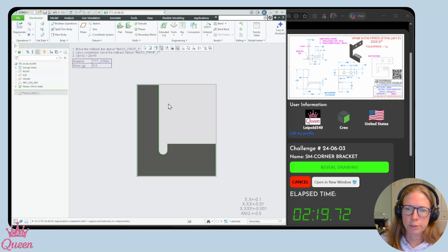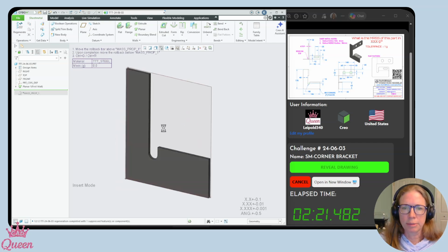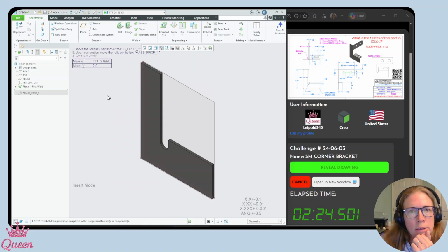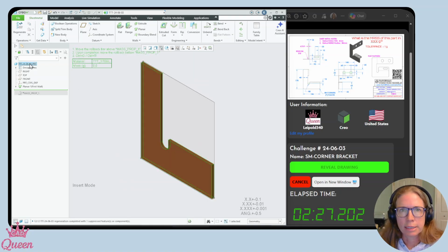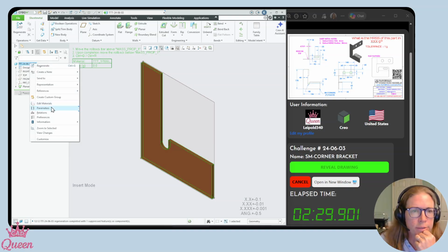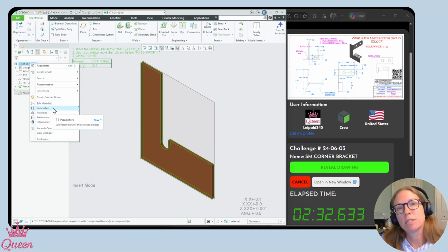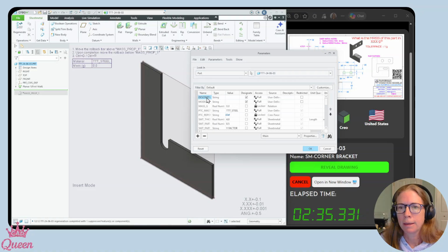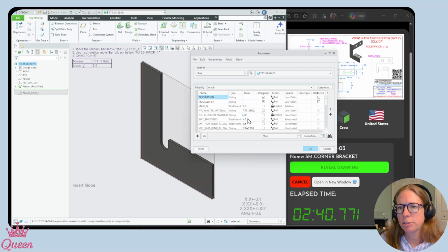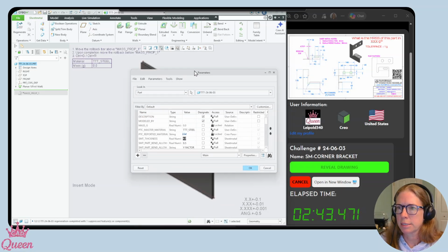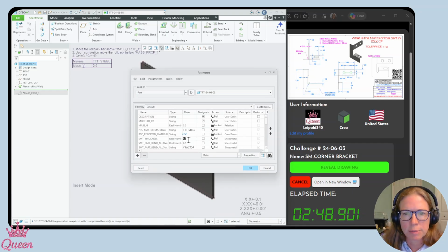Okay, so there's our planar first wall. Normally these are going to be green. Let's double check the thickness. And this kind of hides a little bit. So I can go into parameters associated with the sheet metal part. And I've got that the sheet metal thickness should be 4. The sheet metal thickness is 4 for this part, default wall thickness. The bend radius should also be 4. Default bend radius here is 4. That's good. You can see I have the steel assigned.